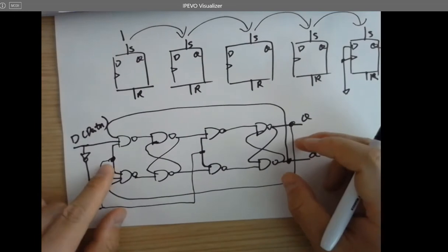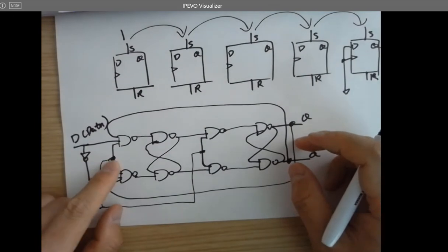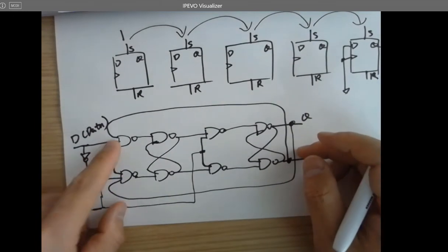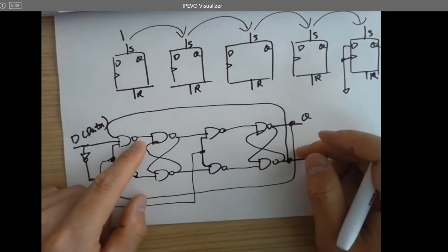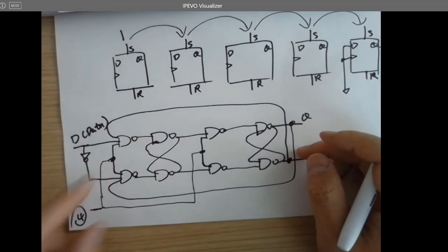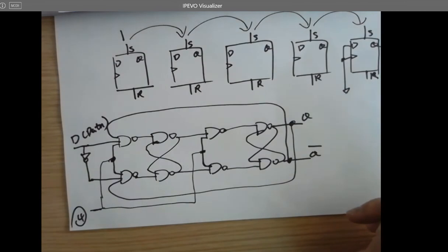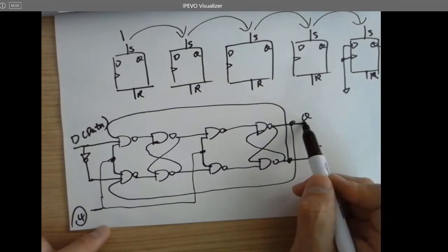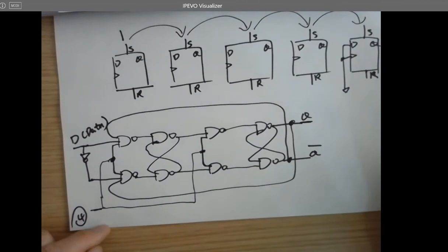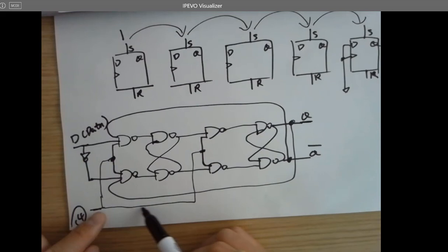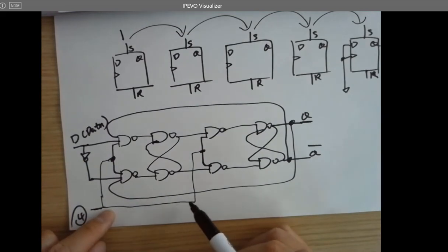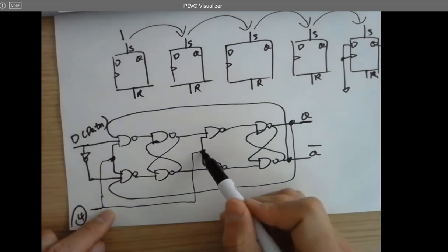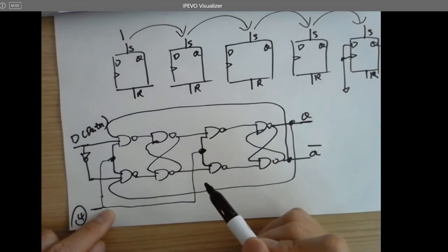So do we want to directly connect the clock to the clock signal input for the first stage of the D flip-flop, or invert it? Because it's falling edge sample and rising edge send it to Q, you want the clock without being inverted. So the clock should be sent directly to the second stage clock.